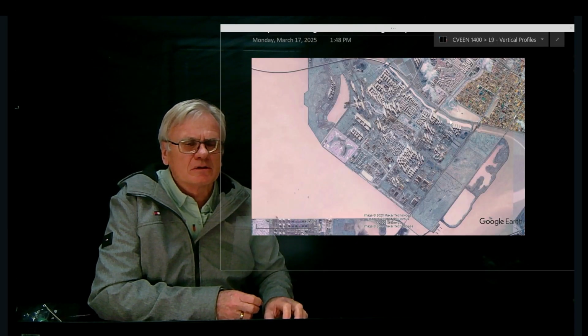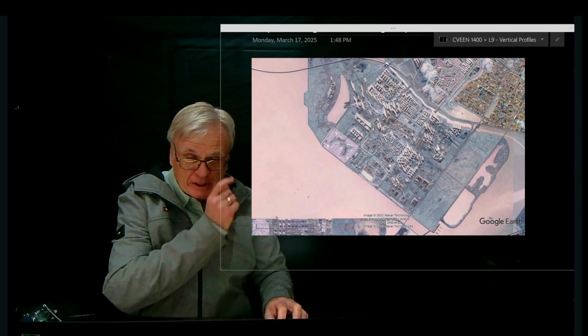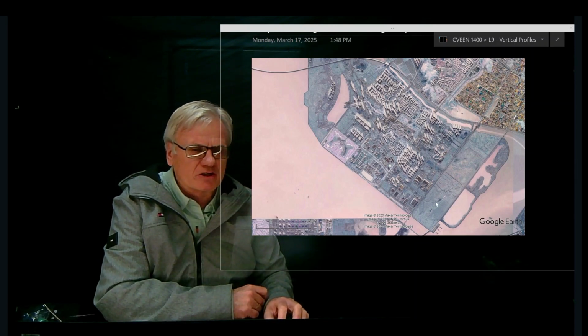So you're looking at the island of Songdo. This is all reclaimed ground here, meaning that this has been dredged. There's been a seawall created out here, and then the dredgings are placed behind the seawall. This is done in phases or stages, as you can see, and you can create new land.